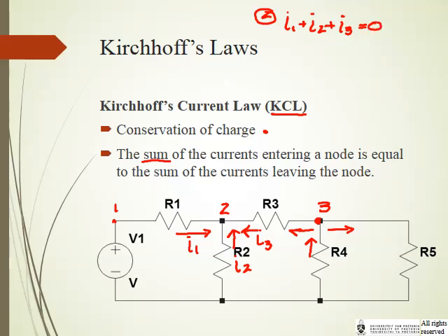All right. Then at node number 3, if you write down Kirchhoff's law at node number 3, all the currents that come in must equal the currents that go out. So what are the currents that go in? There's only one. So here we've got I4. This one we'll call I5 as it goes through resistor 5, and this is still the same current as on the other side of the resistor because it's through the same resistor, so it's also I3.